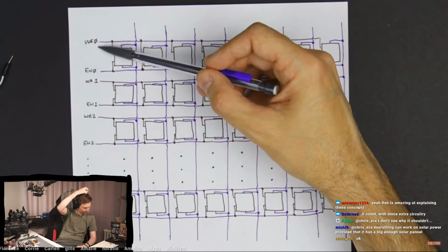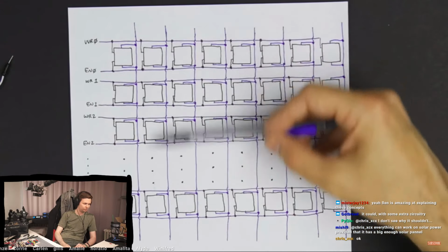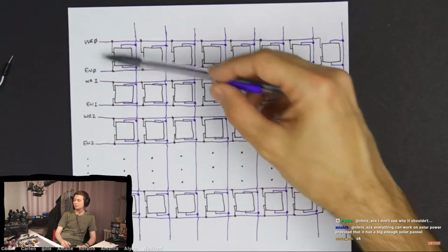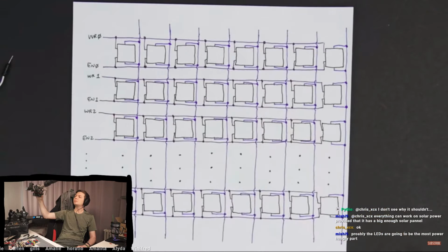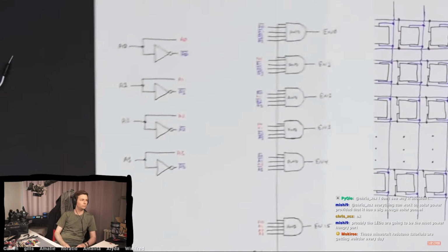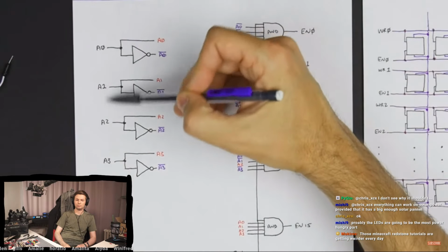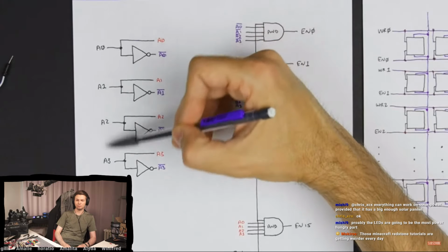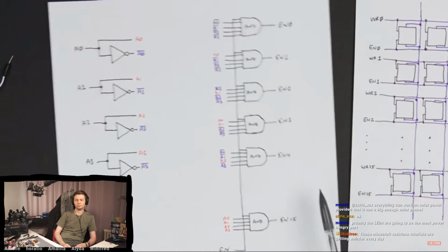So what we'd like to do is be able to encode which of these 16 bytes we're reading or writing from using an address, because you can represent a number from 0 to 15 using just a 4-bit address. The way we can do that is using this address decode logic, where we have 4 address signals, and these 4 bits essentially represent which of the 16 bytes in memory we want to talk to.